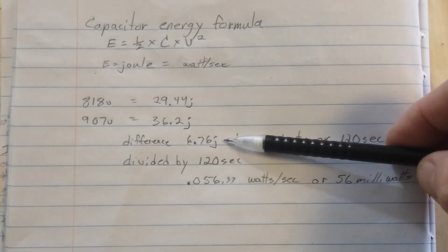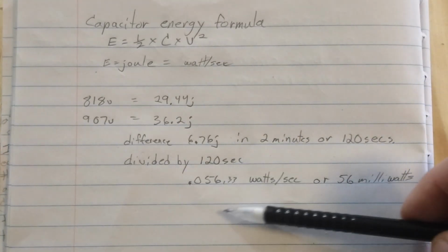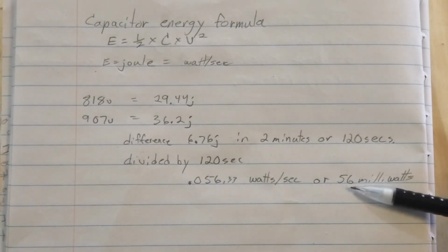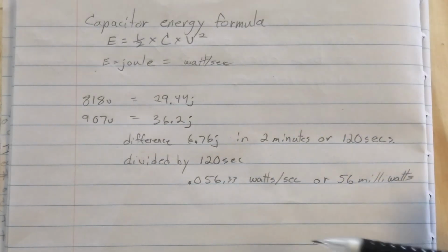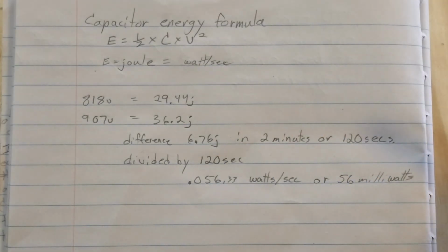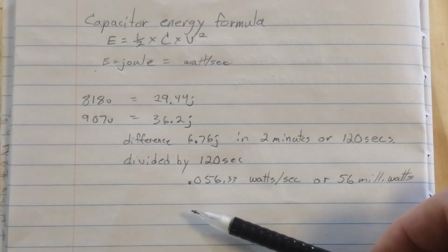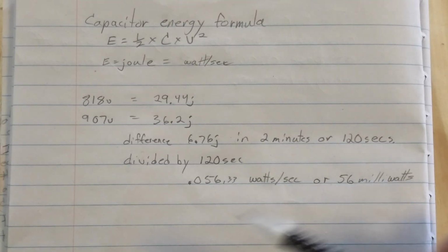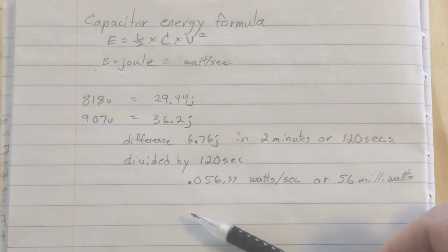So we can just take the difference in joules and divide it by 120 seconds and come up with an answer of 0.056 watts, or 56 milliwatts of continuous power. So no, you're not going to be able to run a house on that, maybe some LED lights. If a fence under a power line had any significant loss, the power company just won't allow it. And this is very insignificant compared to the whole capacity of the power line, because the fence under a power line is being grounded out.